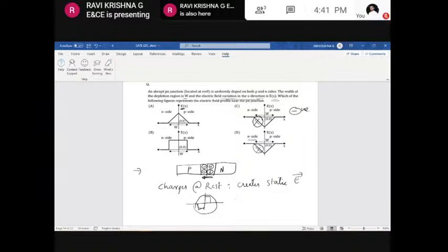charge distribution here, because first we need to understand the charge distribution, then we need to get the potential distribution. From this potential distribution, we need to get this particular electric field. So from this, we will get to know this is going to be the correct answer, because we should have some positive value of the electric field, and it should not be like this. It should have some slope. It should have some linear relationship on the N side as well as on the P side because of this charge distribution. So this is going to be the correct answer, and this is wrong.